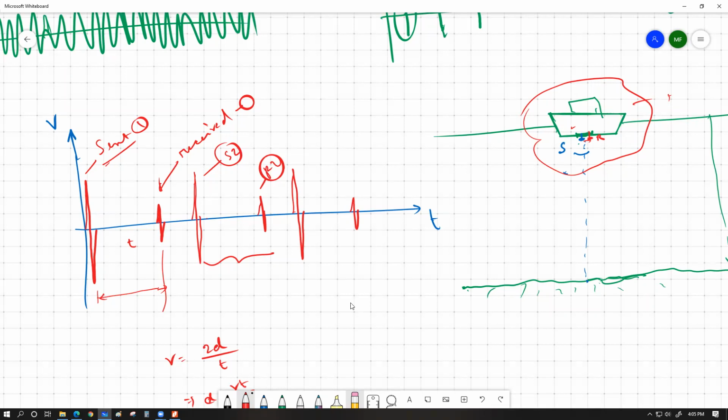What is really important is that we cannot send our second sound before we receive the first reflection. Hear me out on this one. The machine should not send a send pulse before it receives the earlier reflection. This is going to lead to a significant error in measurement.